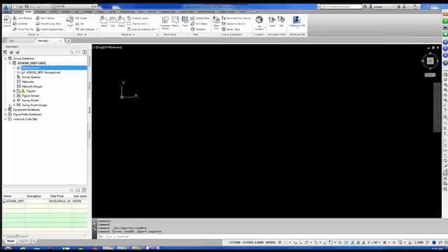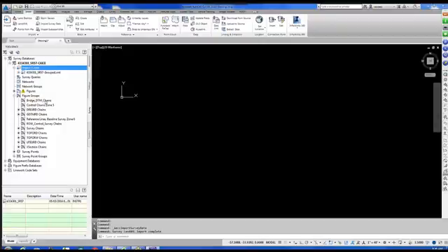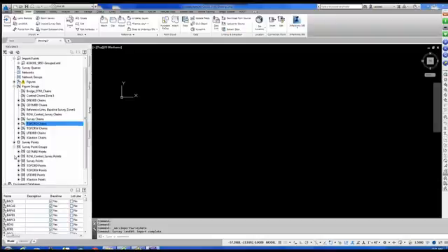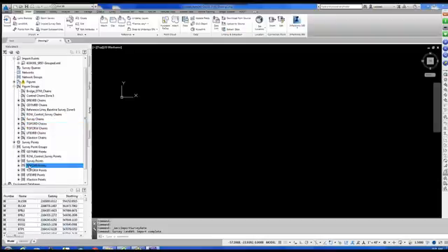All right, so now, over here under Figure Groups, those are the groups that we told the software to create by using the LandXML grouper. So we've got TopoRD chains, and we look down here in the preview, these are the chains that we looked at. If we go down here under Survey Point Groups, under TopoRD points, those are all the points that are part of that group that we made by using the filter in the LandXML grouper. Okay? That's why we do this. If not, all this data would have come in. We would have had one figure group and probably one survey group, and that's it.